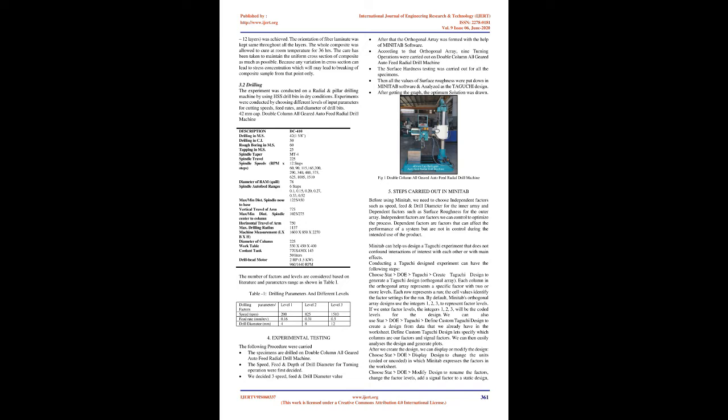Taguchi styles recognize that not all factors that cause variability may be controlled. These uncontrollable factors are known as noise factors. Taguchi styles try to determine manageable factors, control factors, that minimize the result of the noise factors, i.e. planning a product or method in such a way as to make its performance less sensitive to variation thanks to uncontrolled or noise variables that aren't economical to manage.